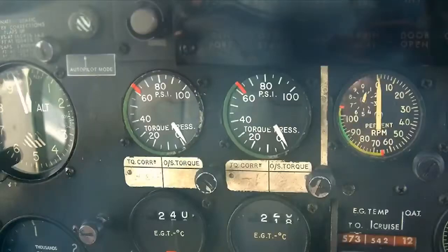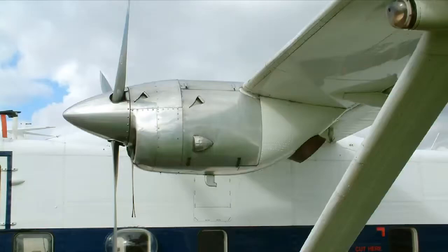A torque meter can be provided to give the pilot information about the amount of power the aircraft engines are generating during any phase of flight. The instrument may be calibrated in units such as pounds per square inch, pounds-feet, Newton meters, brake horsepower, or any other suitable unit of power. Either electronic or hydraulic torque meter systems can be found in service.